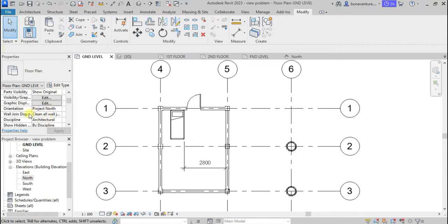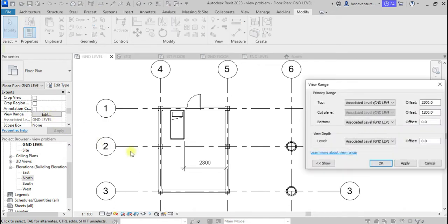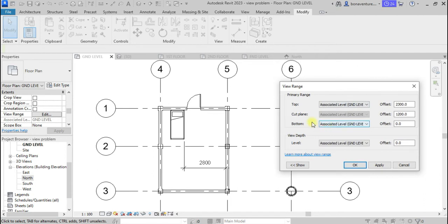We're going to view range, coming down. Now either you click view range, or you type VR, the shortcut for view range. Now coming to this page, you see that our view range has all these levels, and view range is interesting and can be confusing, especially if you don't understand what value to put, and what these different levels stand for, and how they affect your plan.